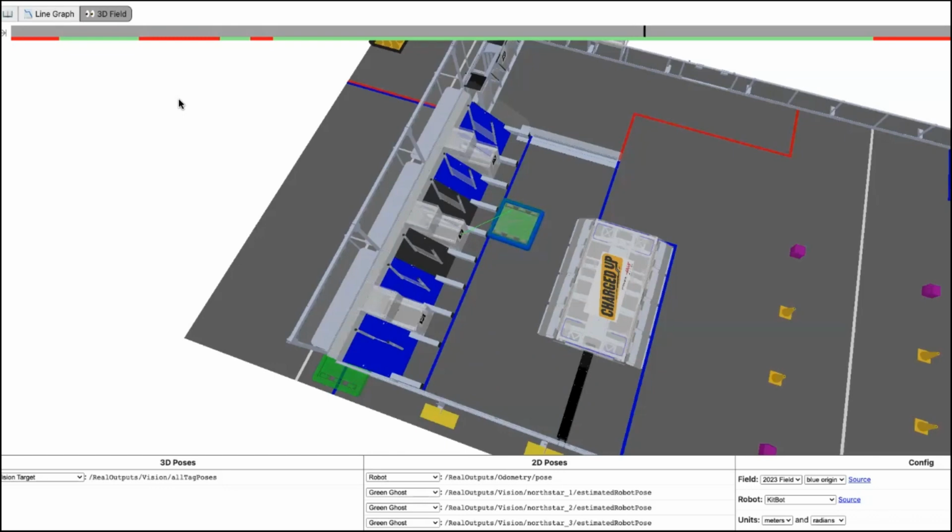When you're talking about scaling your standard deviations based on distance, that's something that we do. We do the square of the distance from the actual AprilTag. So if we have something like 0.25 for our standard deviation, that might become 1 or 1.25 if we're 5 meters or 10 meters away from our actual AprilTags. But if we're really close, that value might just be 0.25. So scaling is really important when you go farther away because you'll have more noise within your AprilTag detection.